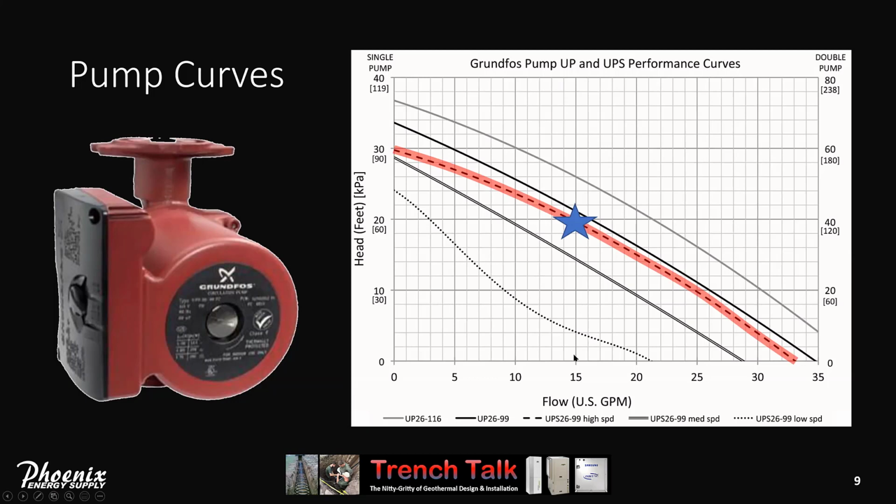And if we look carefully at 15 GPM, we're going to have head capacity just under 20 feet of head. If we put 2 pumps in series, the numbers on the right illustrate the head, and it's doubled. So it's pretty easy when you put 2 pumps in series, they're both going to handle the same flow rate, and they're both going to generate just shy of 20 feet of head. So when you put 2 in series, you're going to be at close to 40.